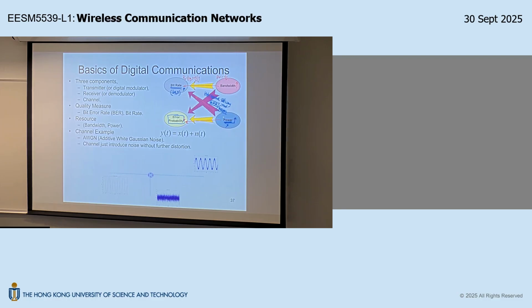the transmit power is around 26 dBm. That means they need 4 dB back off. Okay? But for 64 QAM, the average power is only around 20 dBm. Okay? So have you ever wondered why from the same physical power amplifier you have different power output levels? That's because these different signals require different back off.